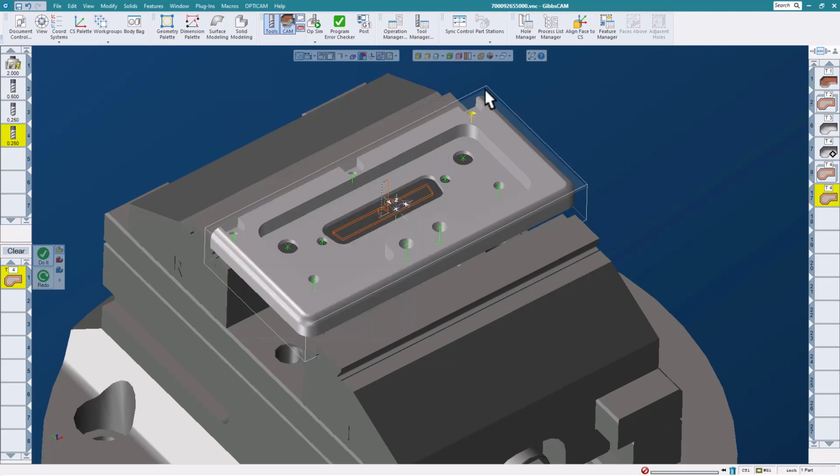Okay. So what we're going to do is use a macro to go ahead and machine a couple of these holes. You can also right mouse click on that when it's highlighted and grab the whole group. So at the bottom here, we say group 3. Then I'm going to go up here and say, go ahead and drill that for me. Now, this particular macro has some stuff we put in there just so I can see what's going on. In this case, it says, hey, that's the size of the hole, and by the way, you're done, because it happens pretty fast. So we want to make sure that we're getting all the things we're getting.